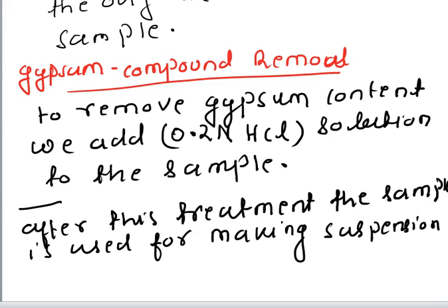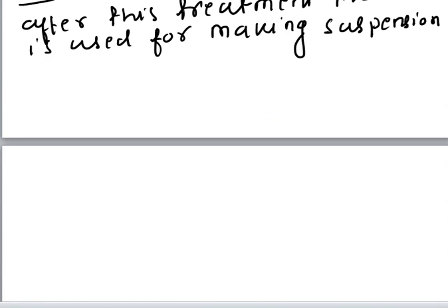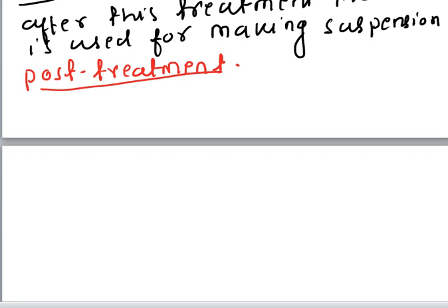So now it comes to post treatment. Guess what post treatment is? Look, as I have said, we are making this sedimentation analysis to find the percentage finer than a particular diameter of soil, and here we are using a fine grained soil sample. As the settling continues in the sedimentation jar, you have heard of the term flock formation, flocculation.